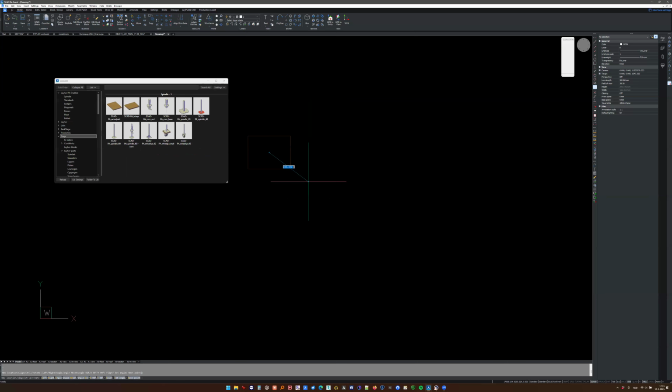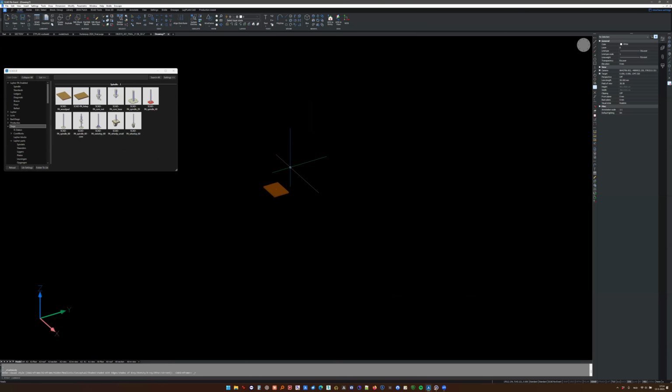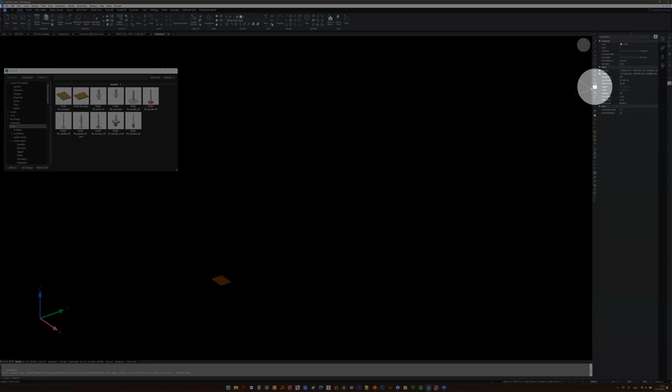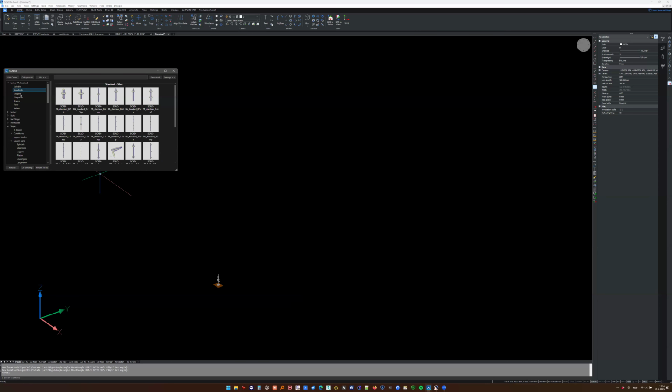When we work with scaffolding objects, I can insert them in the drawing. Let me switch to a realistic view. The key thing is we added points on key positions, so if you work with an entity snap with just points, it's almost impossible to miss by snapping the objects, even when I'm far away. I go to my standards and I click a random one.